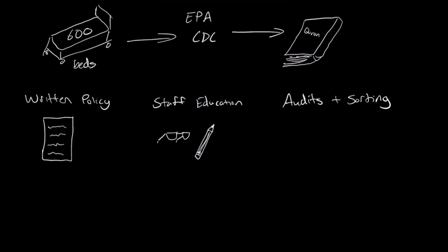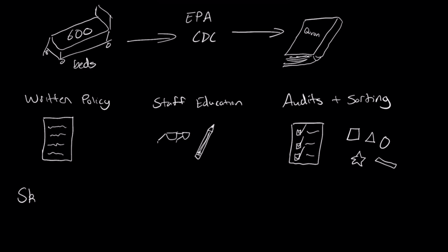This included things like auditing and sorting of infectious waste via those same color-coded bags that I just mentioned. The crazy thing is that this strategy revealed that over 50% of the previously unsorted material was considered to be non-infectious waste once it was sorted. As a result of implementing this program, they were able to reduce their cost per year by 17,936 USD, and that's with 5,262 of that coming from fuel costs from burning incinerators alone.